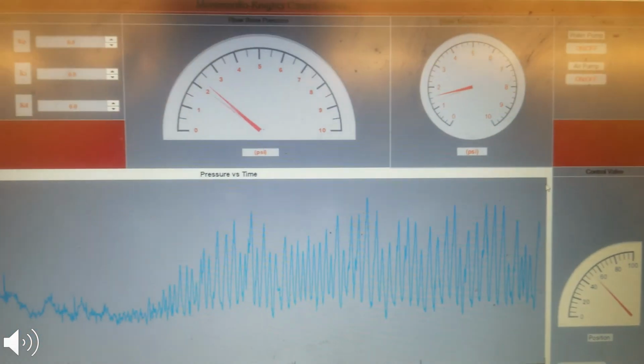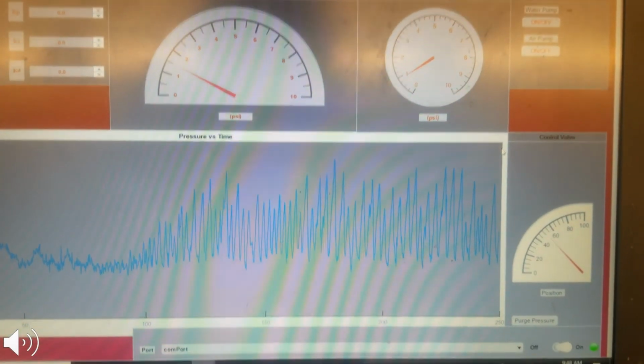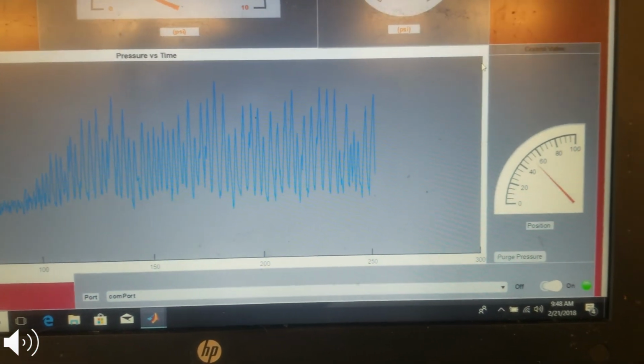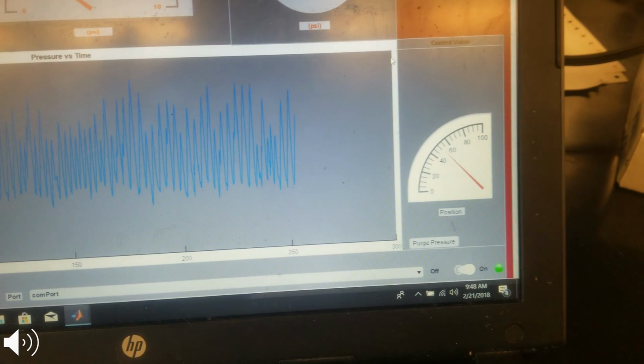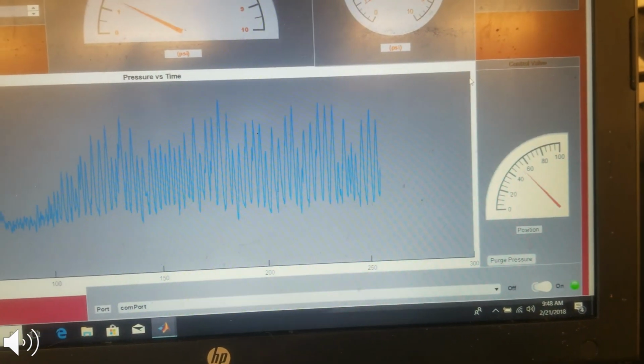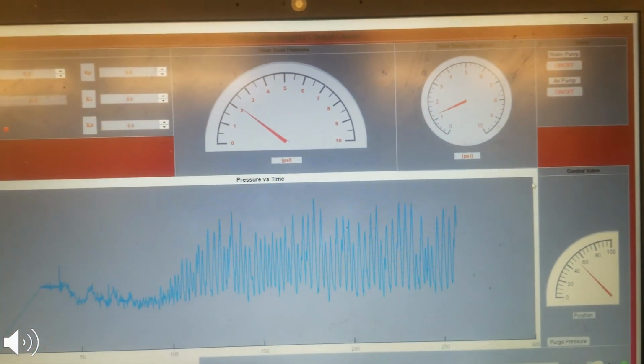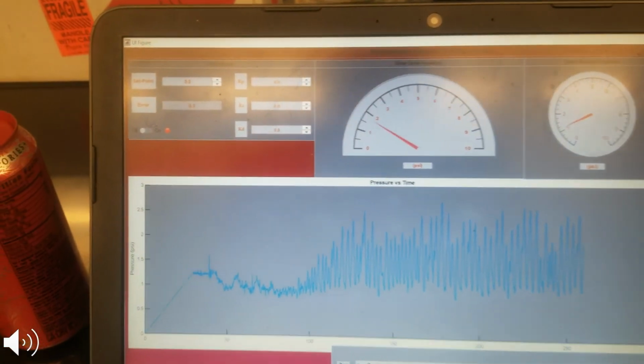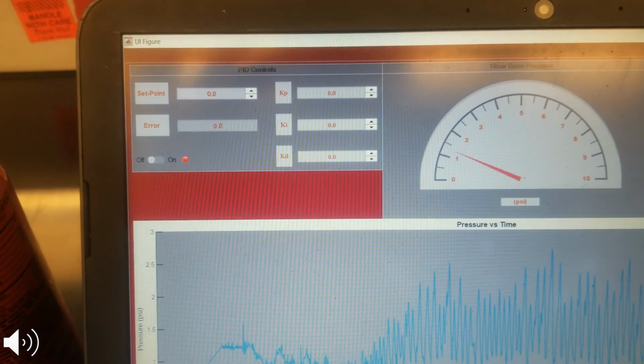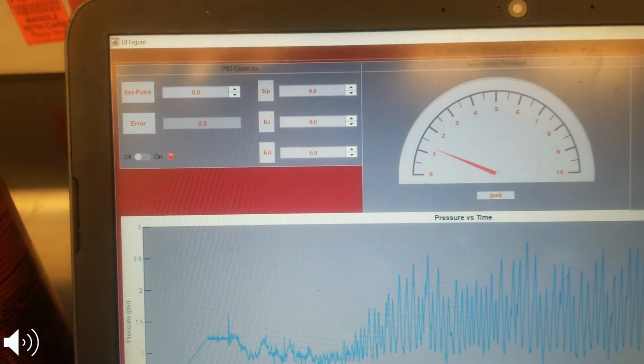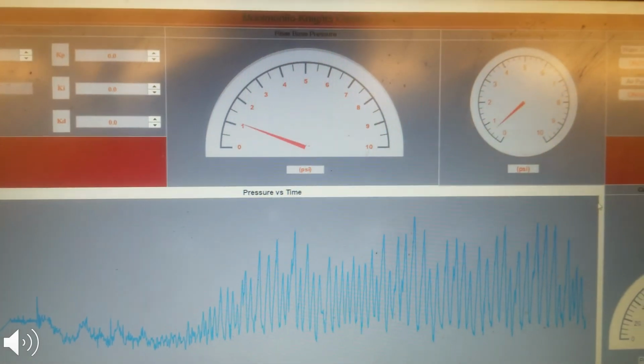To set system parameters and retrieve data more efficiently, the team designed and implemented a graphical user interface with MATLAB. This allows the user a more friendly environment to read pressures and flow rates, adjust PID settings, and initiate emergency pressure purging procedures, and visually see the PID attempting to reach set point on the included graph.